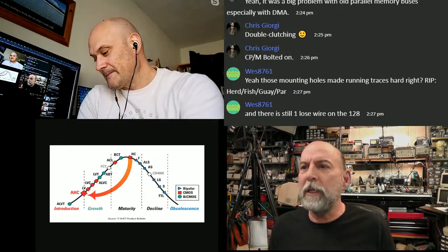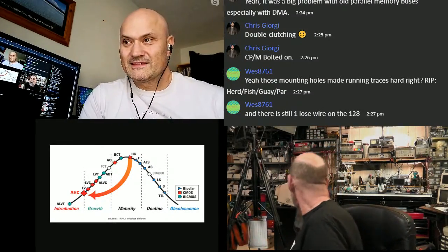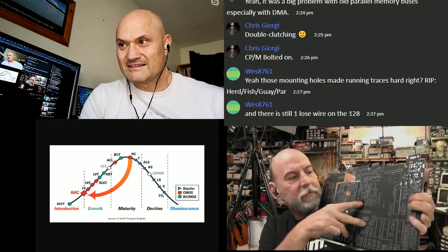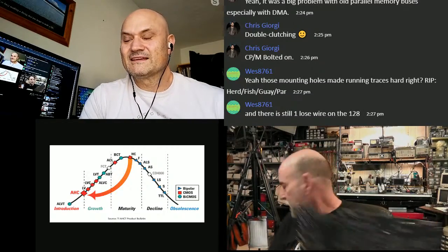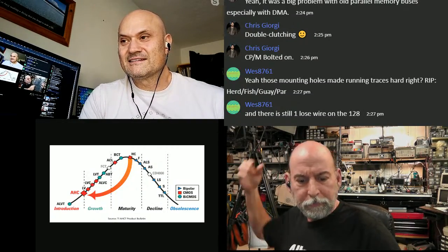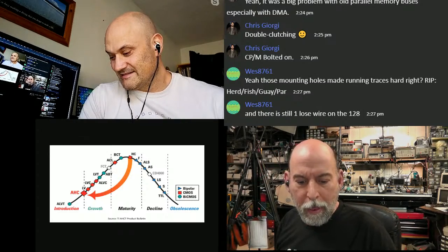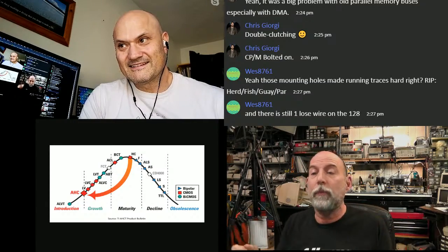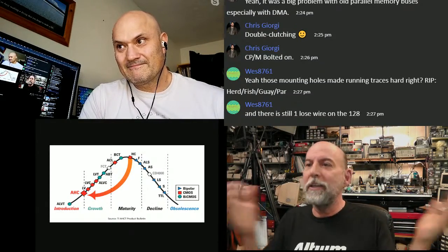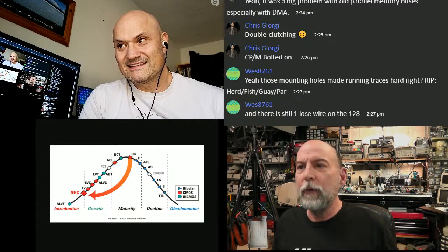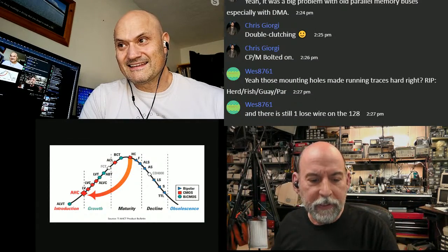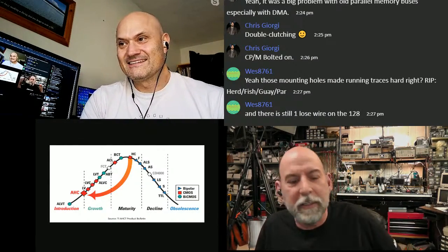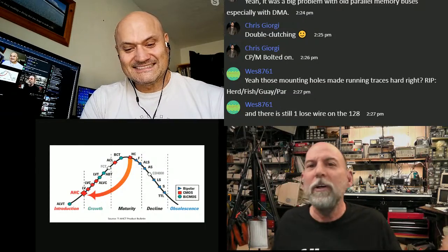And the reason we didn't rev the PC board, this is a packed 2-layer board. There's no room on it whatsoever between here and here. All of the data that goes through there, there's no more room. And I forgot what I was talking about. What'd you ask? Oh, so the reason I didn't rev the board is I might have just moved the problem to someplace I can't fix with a wire. So I said, the wire I know is better than the problem I don't. And that dang wire that we put on all 7 million C128s cost me like $1 each. I probably spent at least $6 million on that damn wire over the course of the project. But it worked. We didn't have to rev the board.